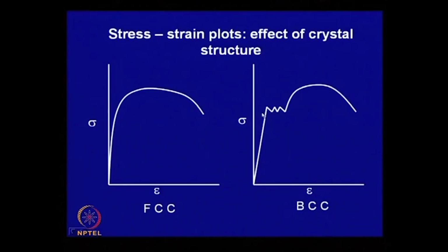An important thing is, if you cold work steel, say you unload it from here, it will come down like this, that elastic portion of the strain which is reversible. There will be a permanent deformation. If you load it again immediately after, you will find that the yield point phenomenon is no longer there, and we will later learn this in detail.